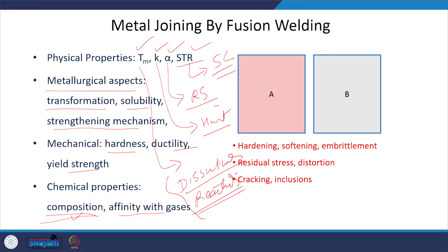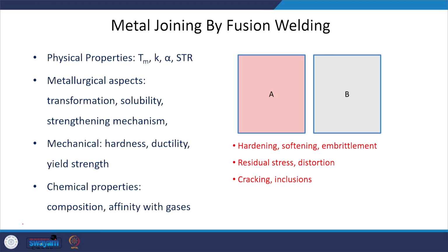In the case of steel, composition is of great importance because it directly affects the carbon equivalent, chromium and nickel equivalents, which in turn affect the phases that will be developed in the heat affected zone and in the weld zone after the welding, and these aspects significantly affect the weld joint properties.